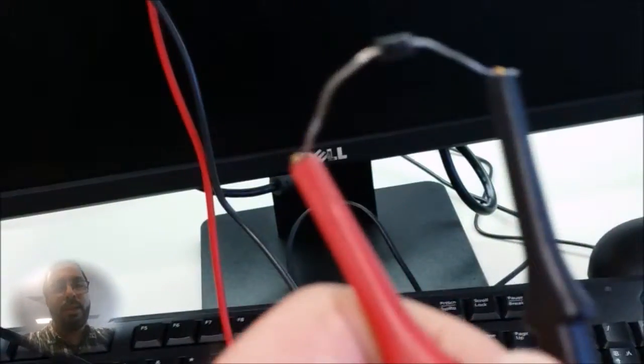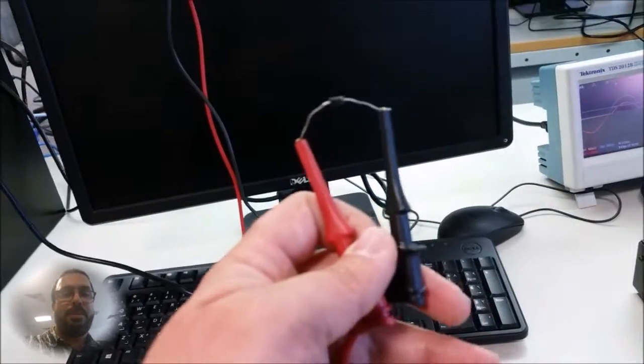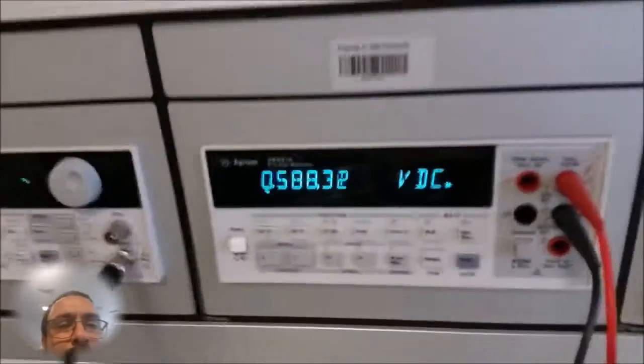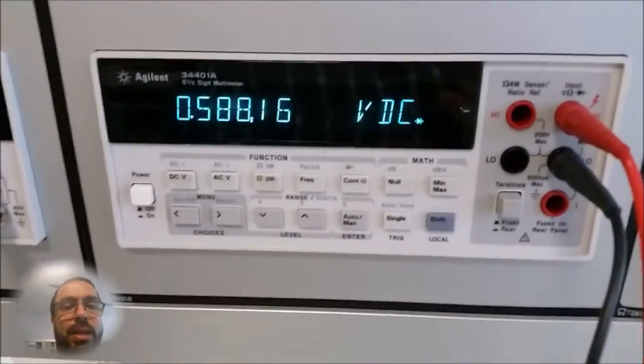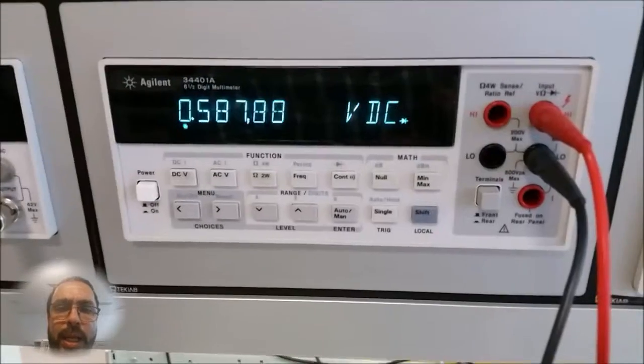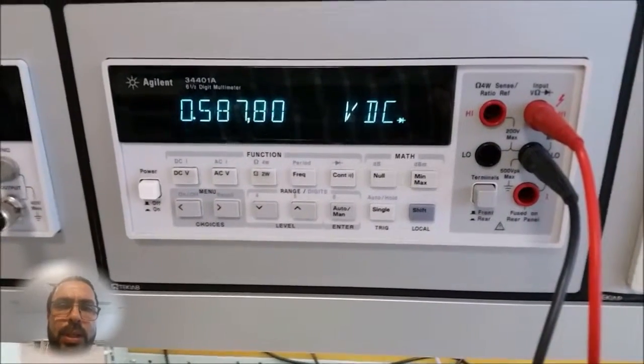So this is the diode. Let's see now, does it focus? Okay, good. Trust me, that's the diode we are trying to use. And using the method that I explained last time, what is that method? By using the multimeter with the diode port, you can see that the so-called barrier voltage is here, 0.58 volt. But what we have seen in the half-wave rectifier was 0.44 volt.